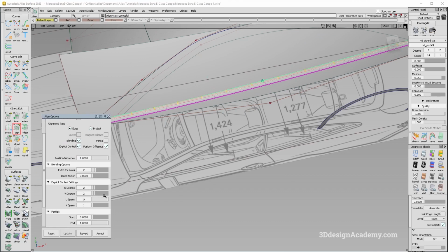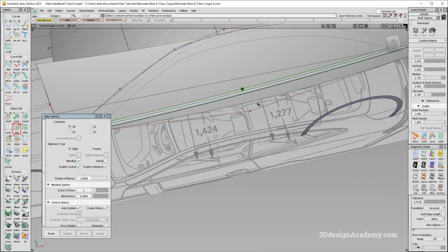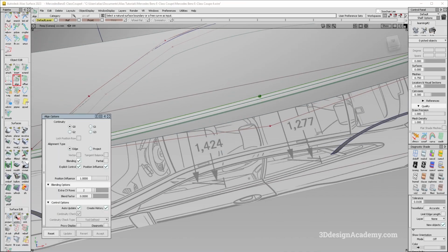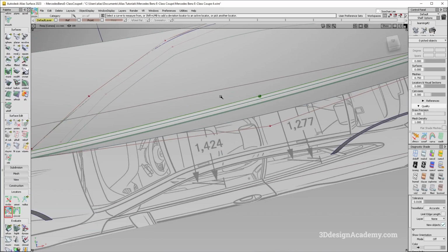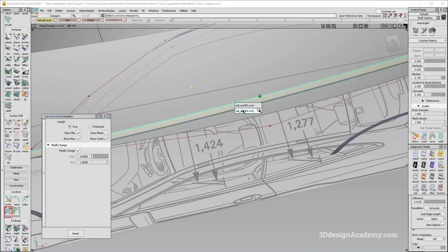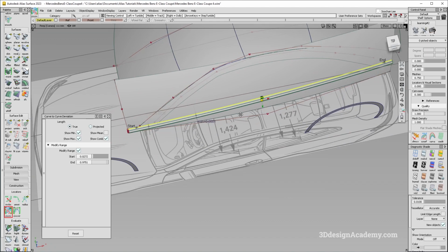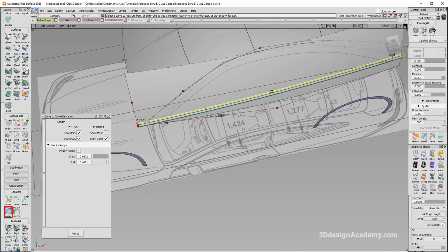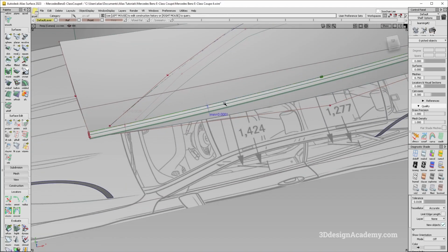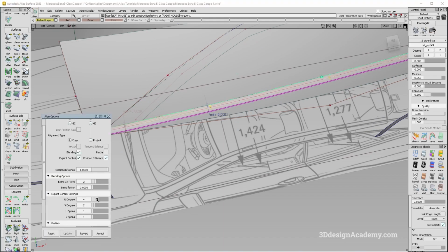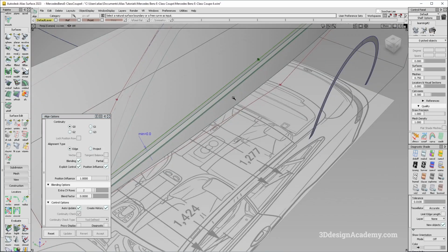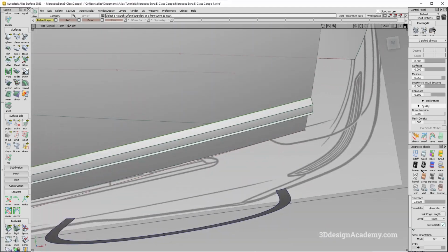And I'm going to go down here and reduce the spans to 1, and up the degree until I can hit the target of position. Okay, so it looks like degree 4 hits it. And I'm just going to check to make sure that it's still a good tight fit. So I'm going to do a curve to curve, compare the distance, and it looks like the maximum distance is 0.0026, which is good. It's not excellent, so I think I'm going to just up it to 5 degrees and call it done. Okay, so 0.0004, that's pretty good. And because everything else is history, looks like everything fit as well.